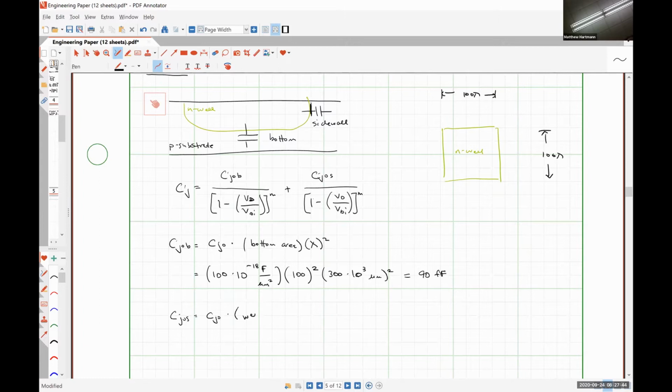So we have in here well perimeter, well depth, lambda. Actually, hold on. Only one lambda. The reason why it's not lambda squared is because our well depth is given to us in the actual dimensions. If we squared it, we'd actually have units of microns cubed.